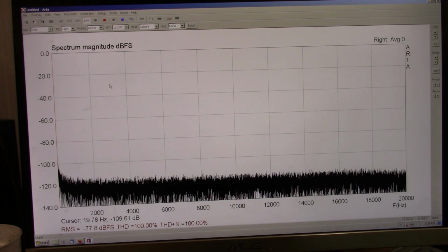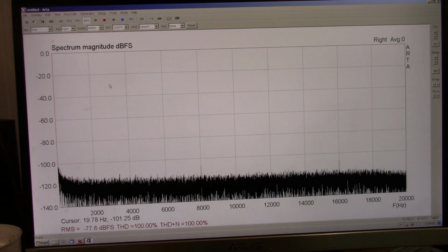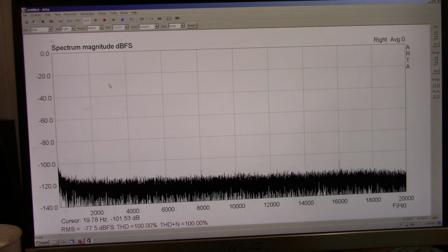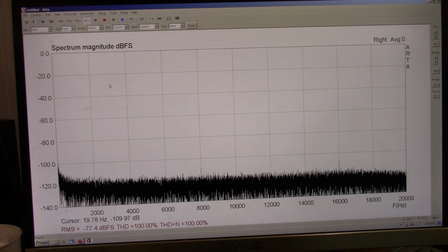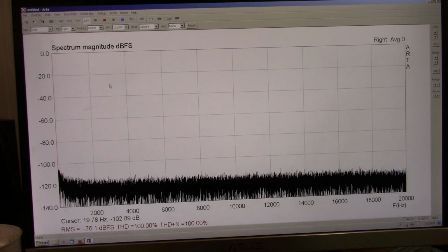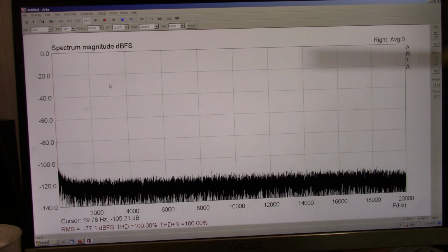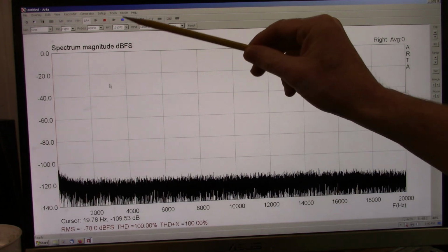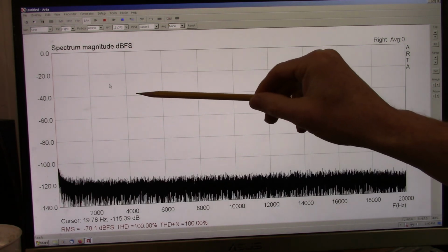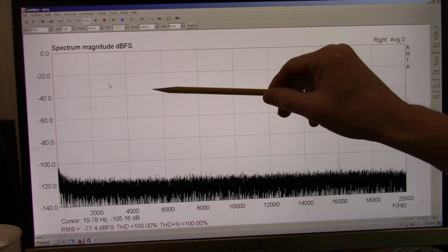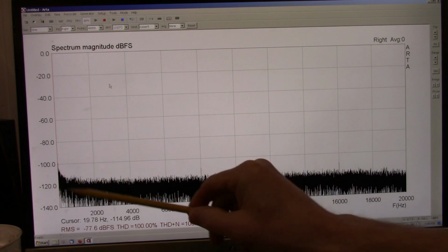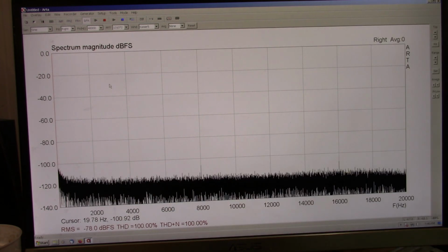I want to make sure the sound card's set up for 32-bit float. I'm not sure if the chip actually supports that. I would think it would. I know some say they do, but they actually don't. That's the amplitude data. You need a lot of bits. If it was only 8-bit, I could only see down to around, not even down to this level, but we're seeing way down here. Noise floor, I'll explain that as well.